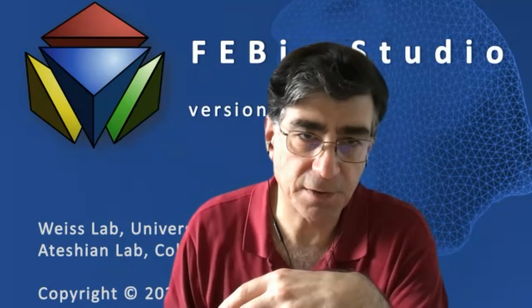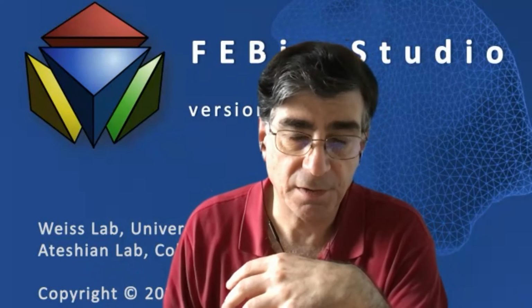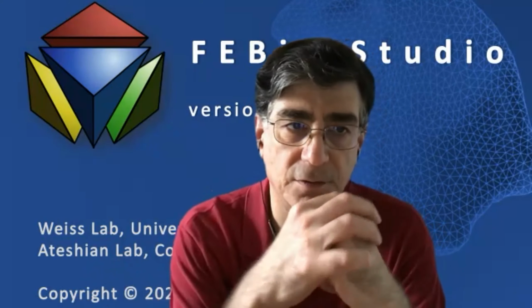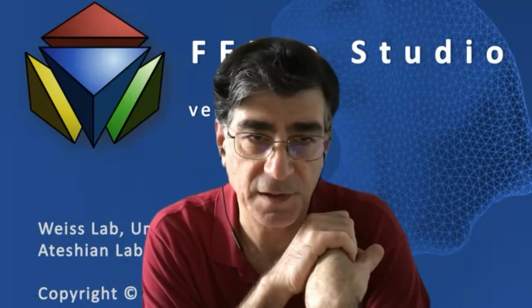Remember, you're just calculating a scalar. So for every element in the domain, you can output the strains and then get the invariants from that. So remember that there's always that capability. You just have to export it, let's say, to an Excel spreadsheet and do the calculation there. Yeah, in that vein, if you're writing your own plugin material, you can also extend FEBio to output other fields that you might be interested in. So if there are specific terms that you're calculating in the constitutive model that you want to look at, it's possible to output those terms to a plot file database.